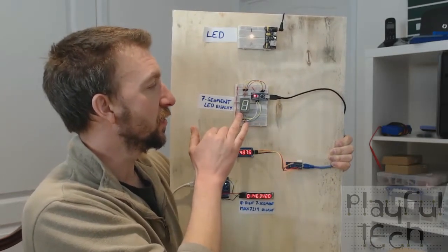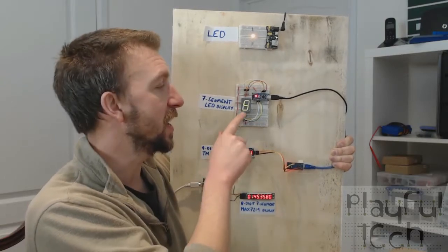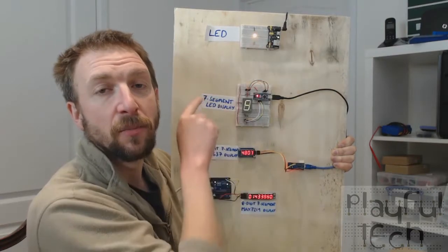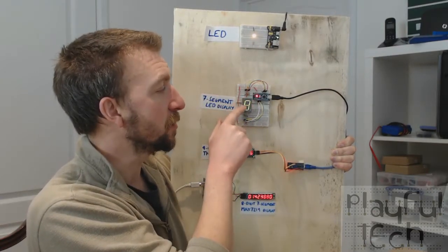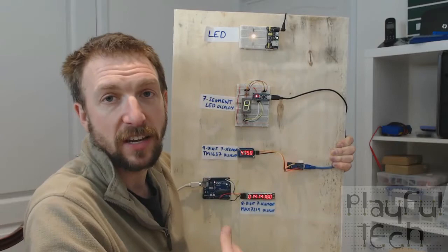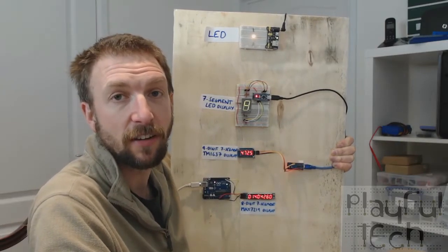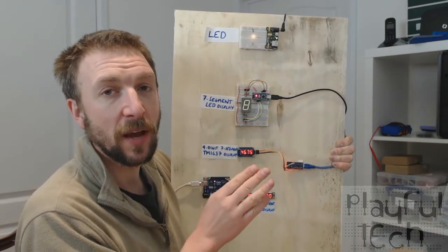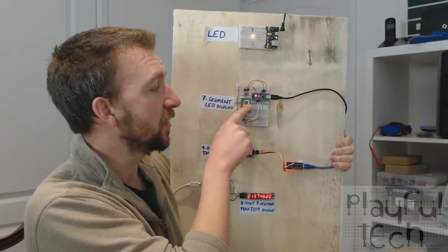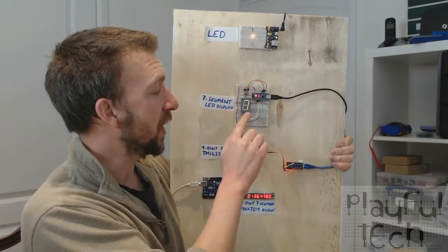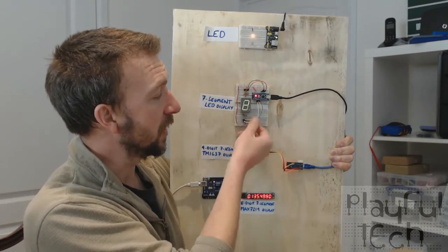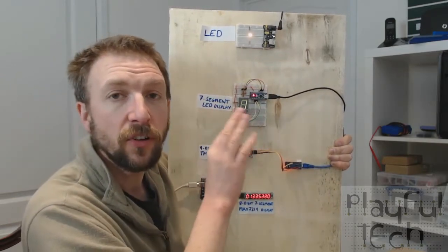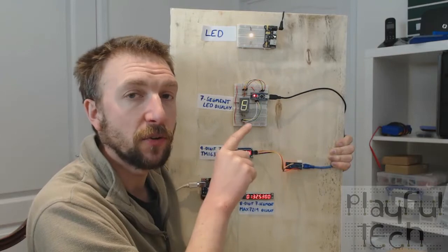Now, what you're looking at here is 7 individual LEDs, just like the one up here, but they've been arranged in the segment shape here so that you can make different digits and some characters as well. Unsurprisingly, every one of those LEDs is individually addressed, so I need to have 7 wires going into it. I've got 3 at the bottom and 4 at the top, and they also have a common wire that's shared between all the LEDs.